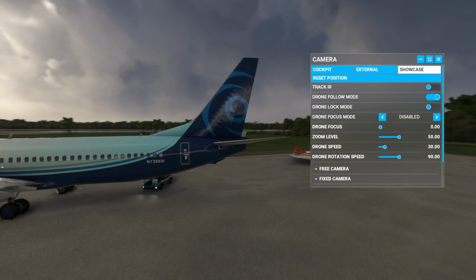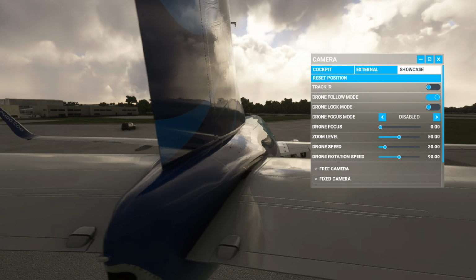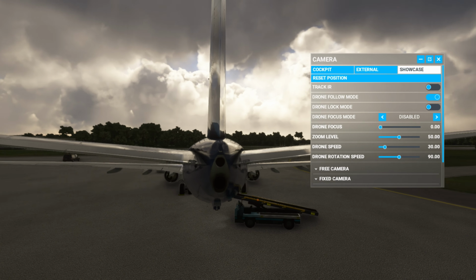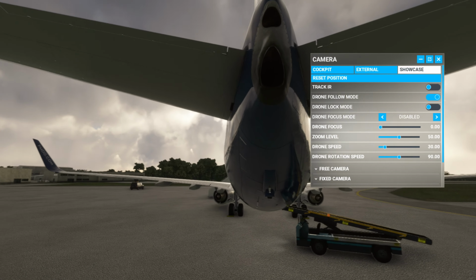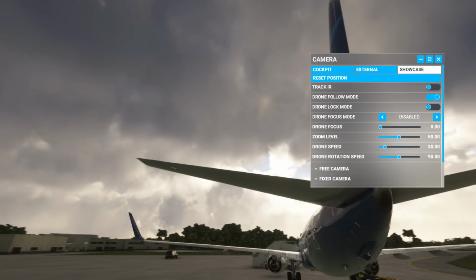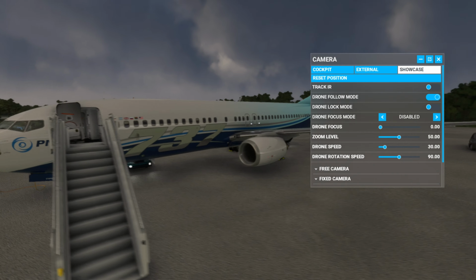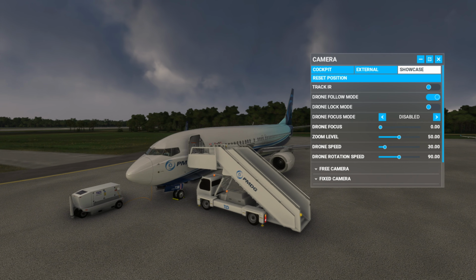As you can see here, we've got obviously a left engine and a right engine, as well as a third engine called the auxiliary power unit. You can see the exhaust ports for the auxiliary power unit here in the tail cone of the aircraft. The auxiliary power unit is also a jet engine. It's a gas turbine engine.